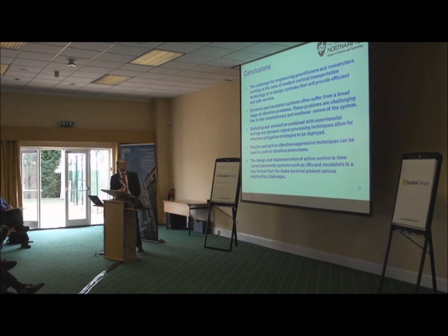We call them non-stationary. When we apply modeling and analytical methods, and later employ computers, and we combine them with experiments and dynamic signal processing, we can develop mitigating strategies. Sometimes they are simple, but more often not. So we can apply passive or active vibration suppression methods. In terms of an elevator and escalator system, typically passive systems do not cover all frequencies. Therefore, we need to apply systems which are referred to as active vibration control.